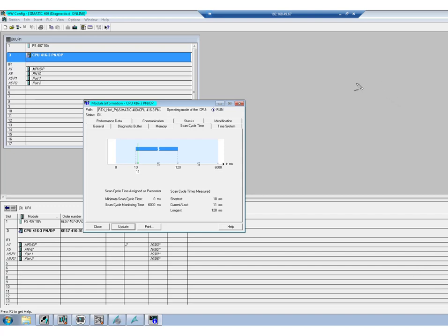Well, of course, in a fixed time cycle, let us say of 10 milliseconds, right? All of the processing time must be done in less than 10 milliseconds, so that after these 10 milliseconds the outputs are available and can be set. On average, let us say that the processing time will be maybe 2 milliseconds. But because of events in the process, this processing time might vary, and in some cases, the calculations might be ready after only 4 milliseconds. This remaining time here, on average 8 milliseconds, but in this case only 6 milliseconds, is allocated to cyclic and acyclic